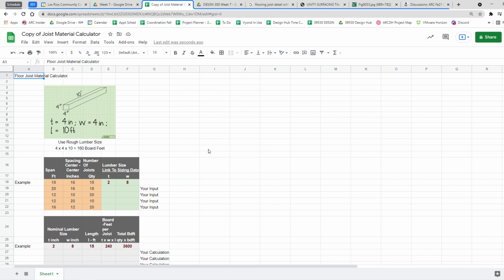So you want to estimate how much wood to order from the mill, and they've got a rough number that they tell you per board foot overall, and then you tell them how much you want of each size, because board feet are inches across by inches deep times how many feet long. So it's a volume measurement. It's just a weird volume measurement.